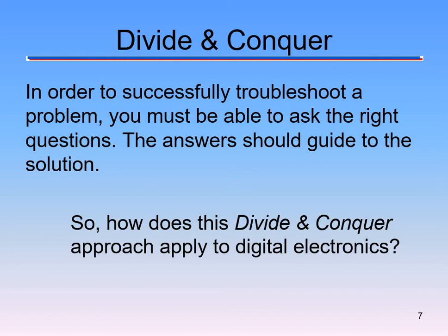Sometimes it's as simple as you've seen me already do it. Hey, is the logic gate working? If I do this and this, am I getting this signal out? I'm just taking a small step to make, you might have 4 or 5 chips on your breadboard. Well, let's see, hey, is the inverter working? So if I put this in, do I get the opposite back out? Test your switches. Are your switches working? Can I turn on a light and turn it off? So just different things like that. The little things that you go through.